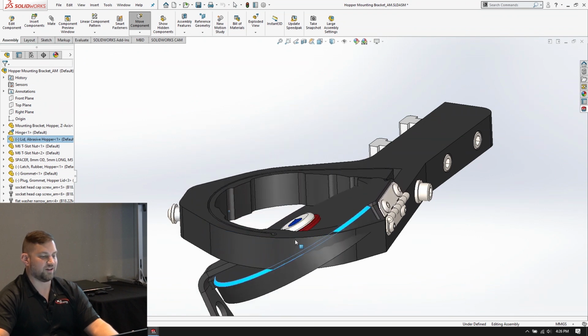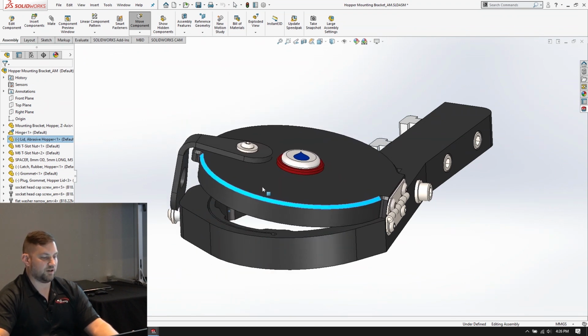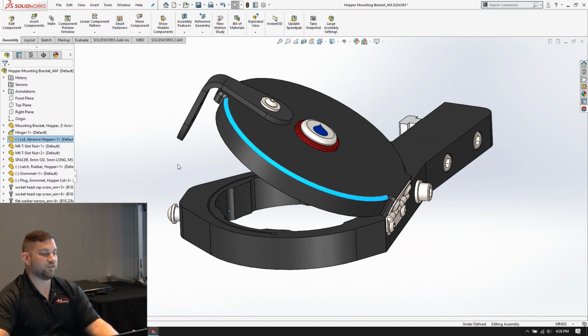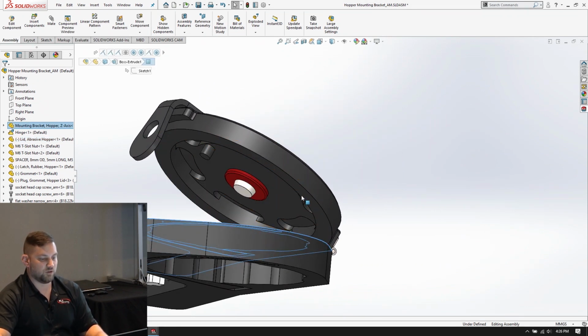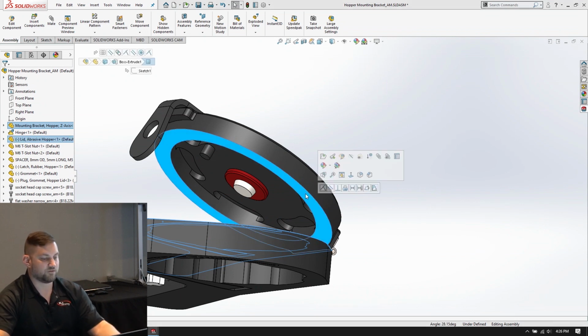You're going to notice that SOLIDWORKS is like, yeah, you can do that. You found the unobtainium and it can go through that model. But we need to tell SOLIDWORKS that it really can't do that. So I'm going to choose that face. Again, using the Quick Mates option, choosing that face, letting go of control, you're going to see that there's now an option for limit angle.